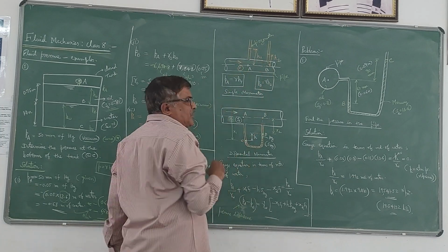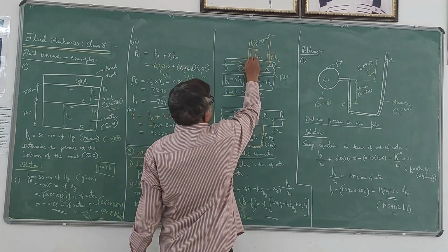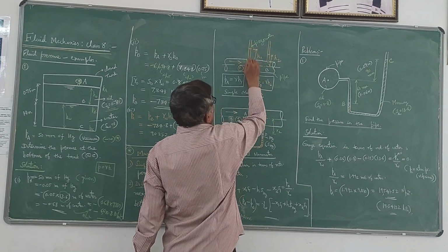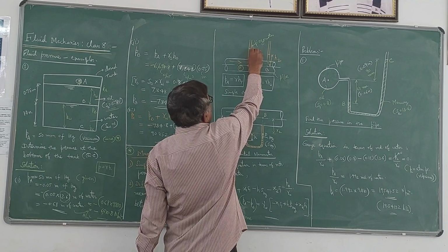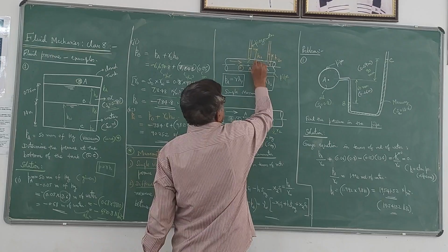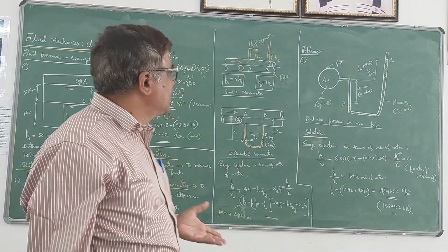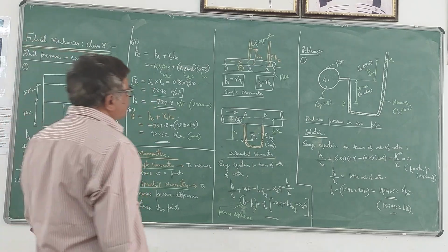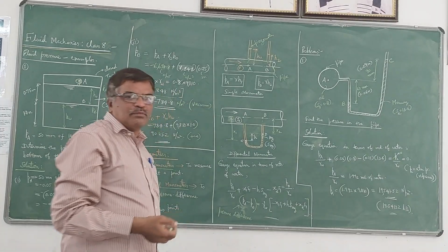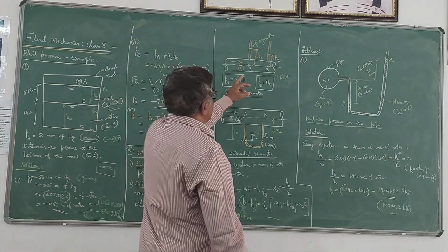So once you insert a tube there at that point, the liquid level will rise here and stand at some point. That vertical distance from this liquid level to the center line of the pipe, I have taken as H1. If gamma is the specific weight of the liquid which is flowing through the pipe, when it is multiplied by this H1, this H1 appears as the pressure head. So gamma into H1 gives the value of the pressure at A.